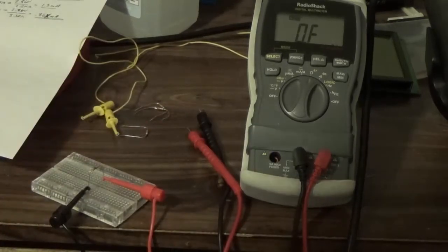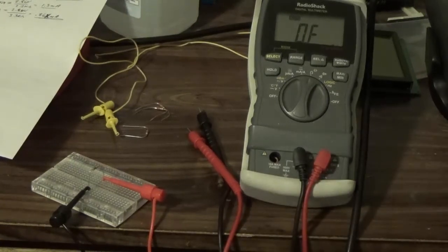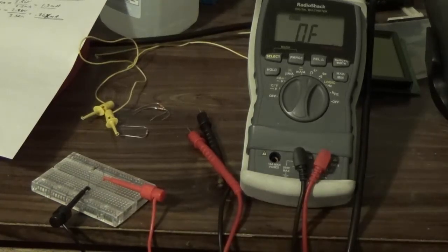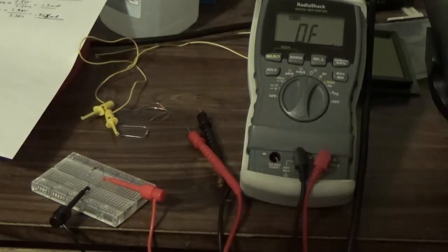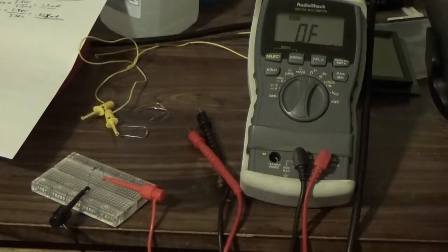It's very hot to the touch, and probably another volt or two, and I would say for sure it would give up its ghost at that point, because this is not a watt rated resistor. Like I said, this is a 1/4 watt, so it's not even good for it to be this high. And the reason we spec it that way is because it's small. We try to suppress the amount of power across it. Anyways, I'm rambling at this point.